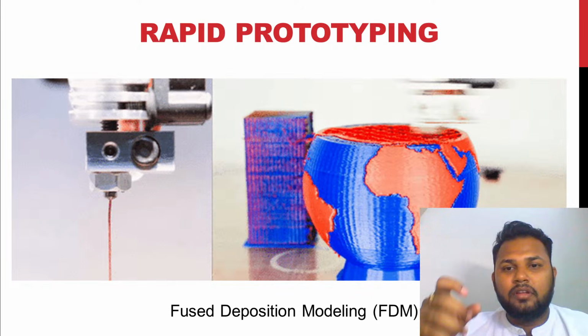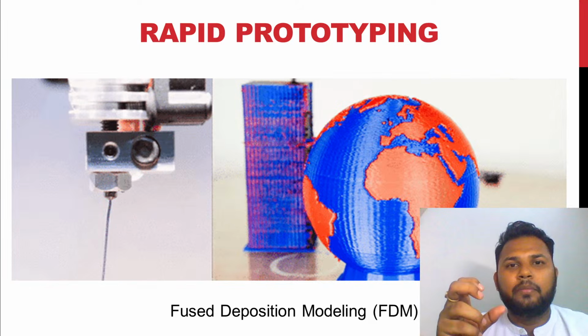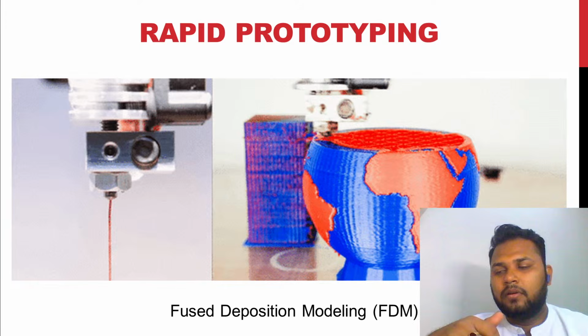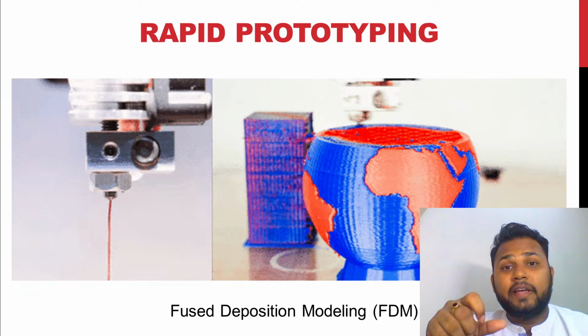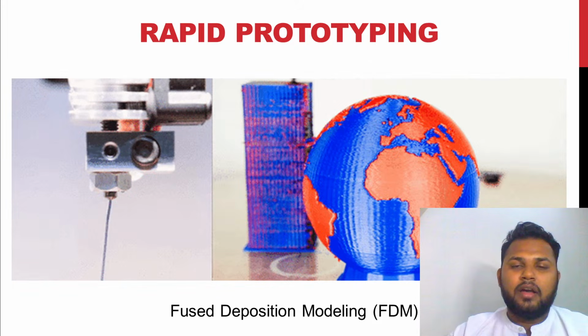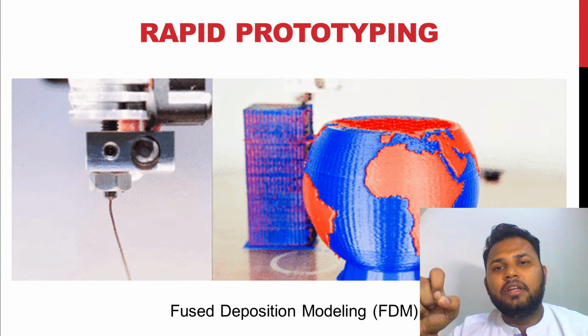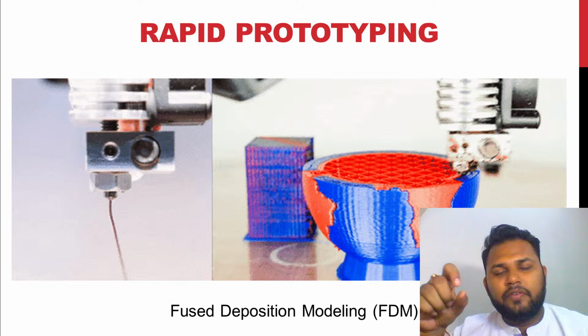If we want to get a smooth 3D print, we will have to recognize what temperature it is actually using for the best printing. So that's why I used to tell people to try from 170 degree initially, from 170 degree to 175, 180, 185, 190 according to your use.